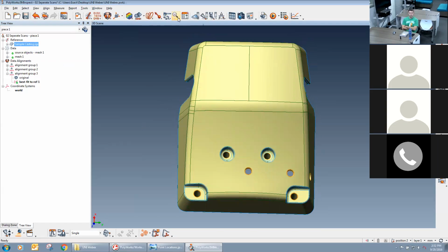Across the top here, there we go, we have a reference target icon, looks just like a reference target. I'll drop that down and we have a couple options here, but the most commonly used one is going to be create surface reference target points. Very rarely would you use one from a feature. You can take them off cross sections, and this bottom one is reference target lines.